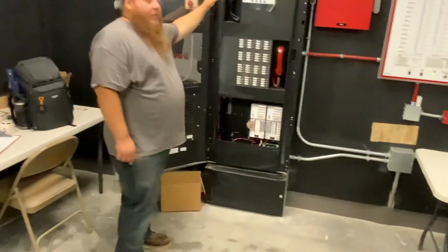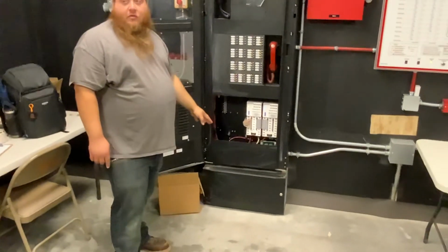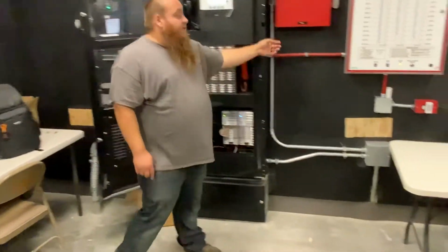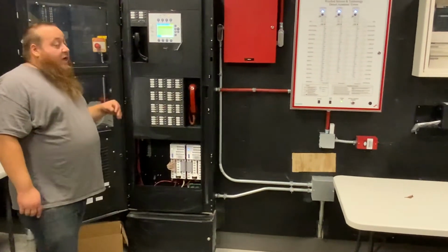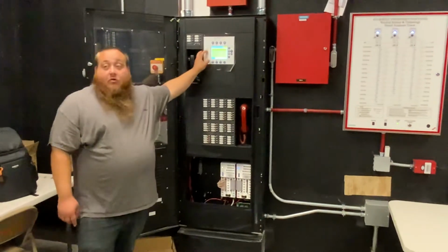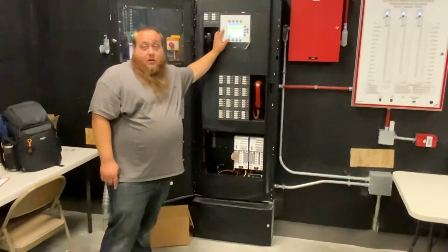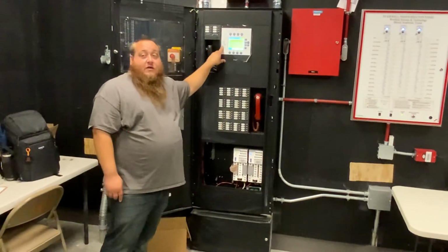Then your batteries are down there. Every panel, like on the 4th floor or 14th floor and 8th floor, will have backup batteries as well. Even our power supplies have backup batteries. So just say God forbid the generator does stop, you'll also have your backup power. If the generator is running, it'll also tell you that your generator is running. You also see this power button now will flash, let you know that you lost AC, but you're on generator.